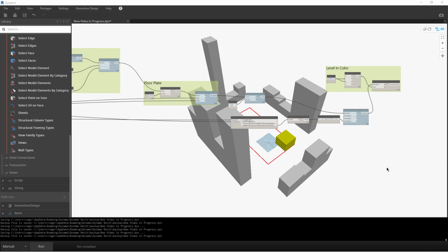Okay, so what we want to do now is create some vectors, views that are going to come basically from the center of the building, looking 360 degrees around, and then determining if they intersect or not to determine whether a view is available through the building. If it doesn't intersect with something, it means you have a clear path through to the next building, so to speak. So we're using that as a basis of determining whether it's a good view or not.